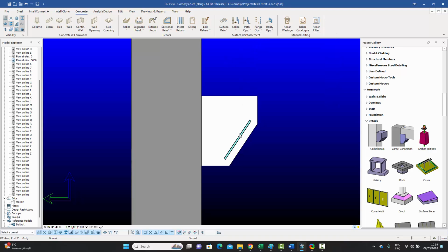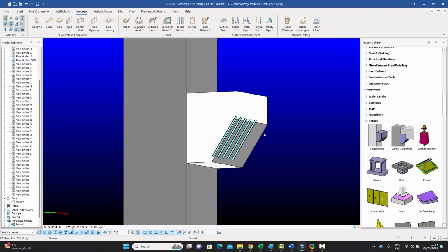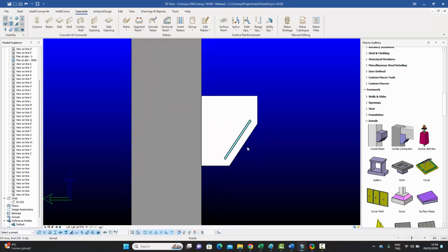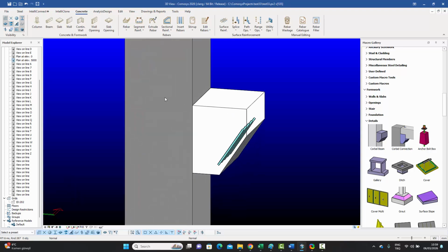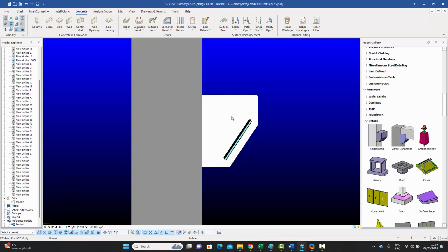So let's say we've got a rebar on this face of the column of the corbel, and we're looking at it from the side. And we want to now embed this end into the column. But we are not on the top surface. The top surface was directly close to the column, but we want the embedment to go from here up, turn into itself, hit the column, and then from that point onwards, we want it to go some number, let's say 35 feet.